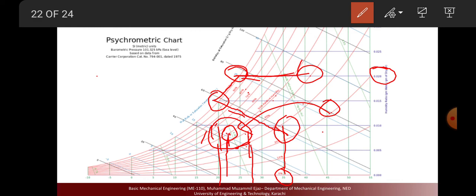But you can see that from the psychrometric chart, by going left, the humidity will not decrease, but after reaching 100% relative humidity, the water is expelled from the air, and then the point of the air goes down in the vertical direction. If we are going in the vertical direction, the actual humidity present in the air is decreasing.